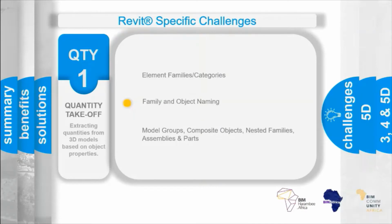out the 3D model. So where possible, object type naming should accurately describe the shape, the makeup, the material, and if possible, the sectional dimensions of an object. Sectional dimensions actually are very important, and if they're modified, this should be done by creating a new object type with the naming appropriately amended to reflect this revised dimension. It's critical that modelers include sectional dimensions in the object dimension properties, and that these match the type naming.